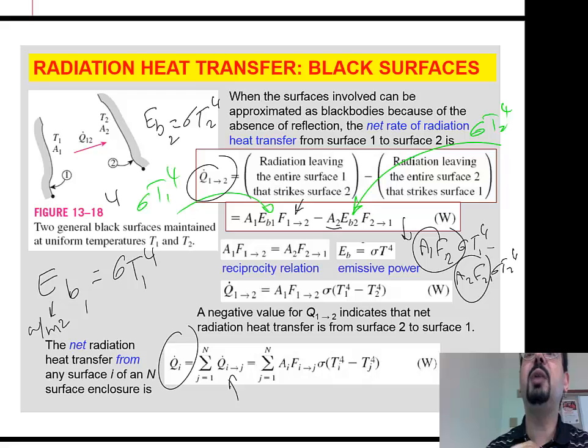So that is what complicates the radiation problem compared to convection and conduction. In conduction, we only conduct to the guy to the right and the guy to the left, right? And convection was only between the surface and the air next to it. But in radiation, at the same moment, you could be radiating to everyone that you see, while you are also getting radiation from the hot source outside, that hot surface that you are also seeing, right? So the calculation becomes really very complicated.